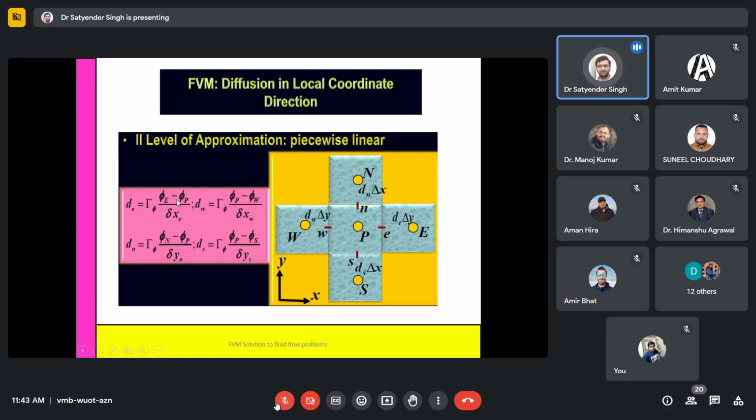like we do for Fourier's law of heat conduction, when we have to find out the total heat transfer considering the temperature difference at a particular delta x, like in the x direction over a delta x distance, we consider 2 points, let's say outlet minus inlet, multiplied by minus thermal conductivity divided by delta x.